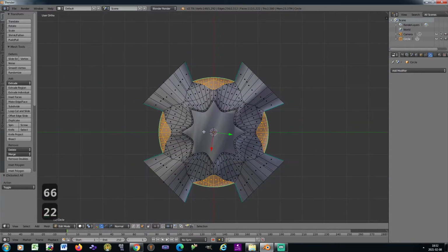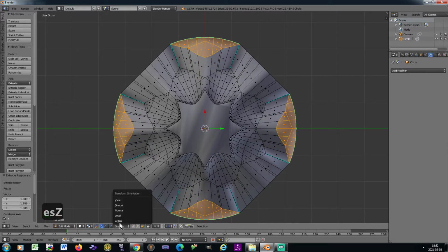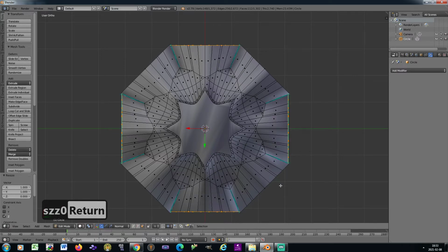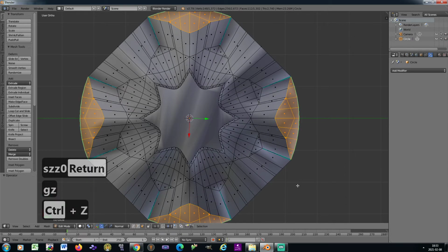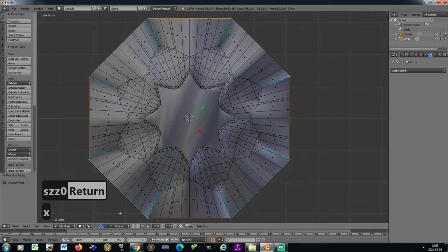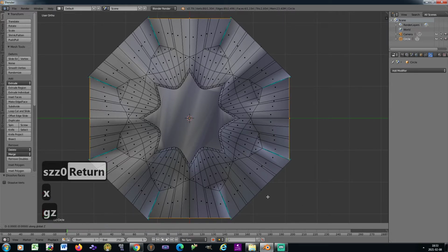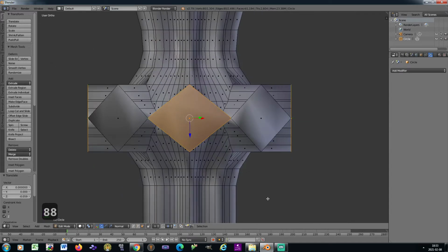Right, we got them all, so again, extrude and scale along the X and Y axis. And scale them down to 0 along their normal Z-axis. Move them up and dissolve faces. Move them up along their Z-axis so they're even with the others.